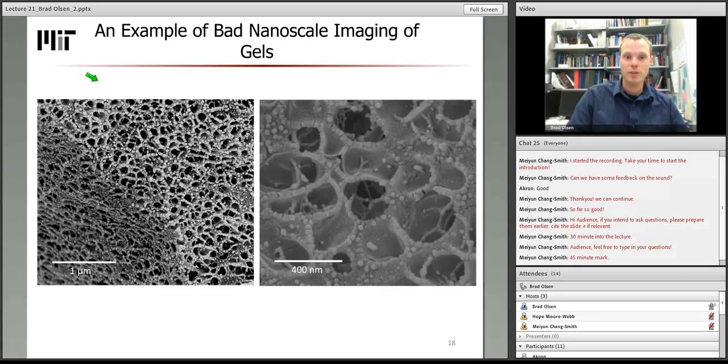These gels are very optically clear, and they show no signs of pores by other techniques. We can furthermore tell this is an artifact by changing the preparation condition and seeing really the same type of structure with all the different preparation conditions. And so this is an example of having to be very, very careful with microscopy based on the processing methods to not get artifacts incorporated into gel imaging, whereas neutron scattering has this inherent advantage of being able to do in situ measurements, which I think makes it a very powerful technique for the characterization of these types of materials.